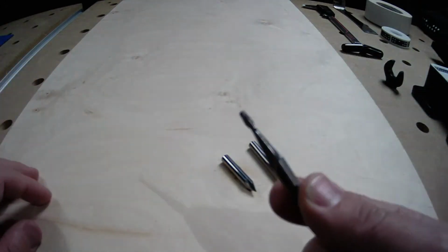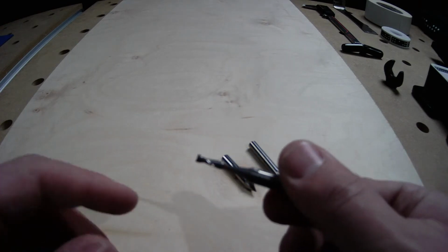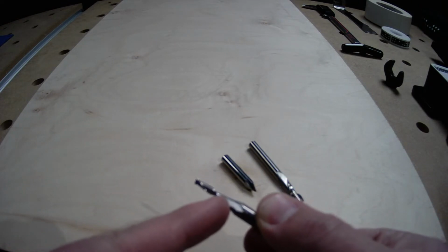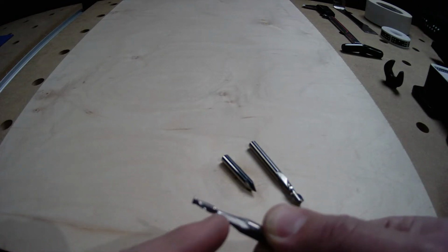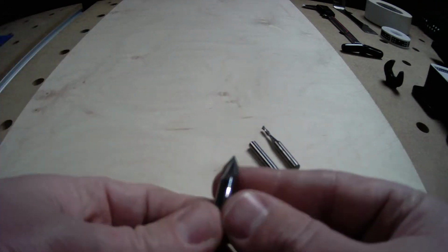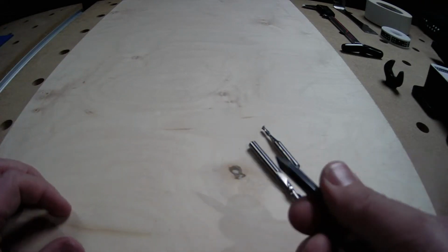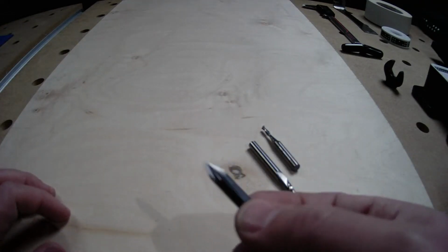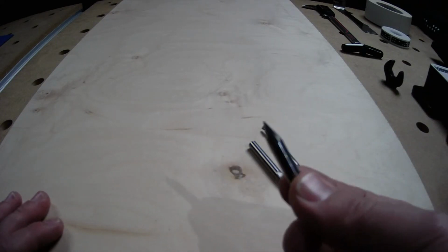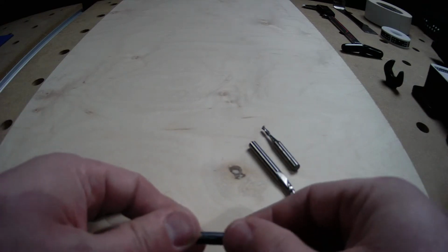This guy is a 1/8 inch end mill by 1/2 inch length of cut. Again, the length of cut is how deep you can cut with this bit, so it can only cut down to 1/2 inch. And again, 1/4 inch shank. And then this guy is the engraving bit that comes with Origin. We use this both for engraving text and designs. And this comes in really handy when you're doing grid work, which we'll look at quickly as a stylus. That'll make more sense when we talk about it a little bit later on.